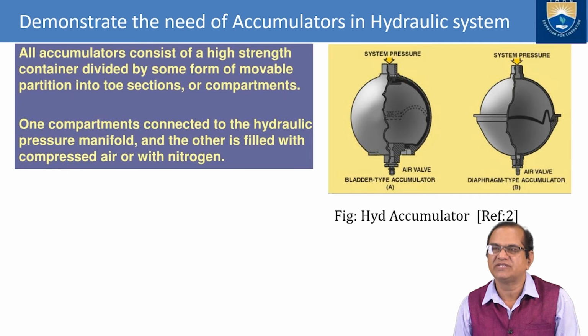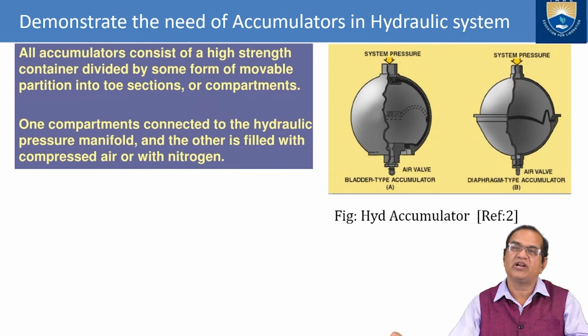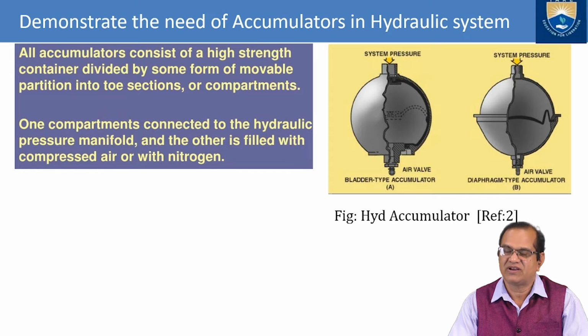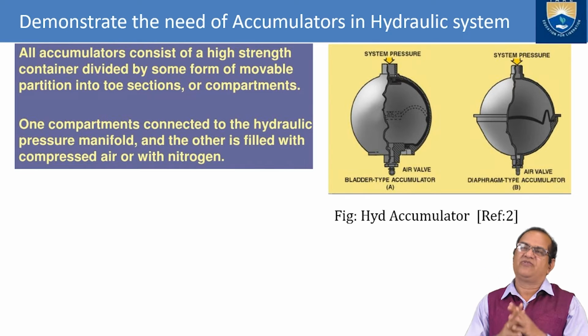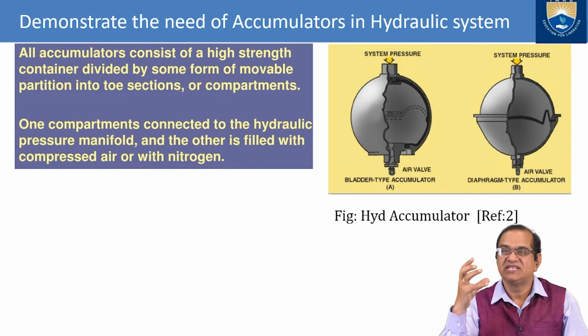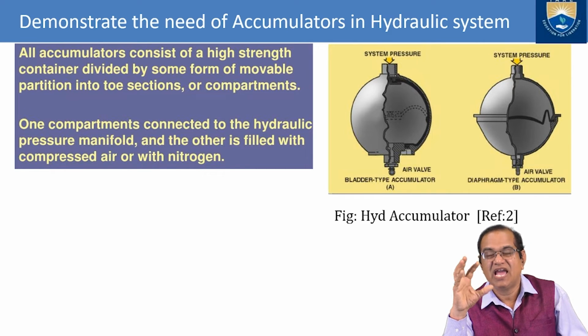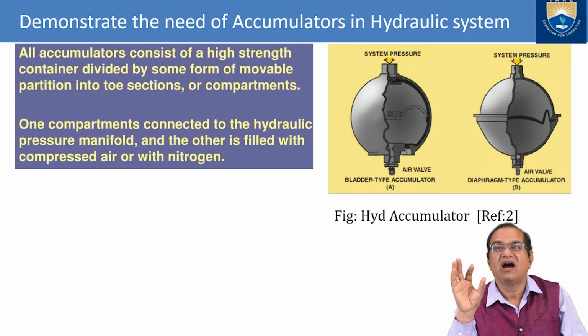Next very important item is to demonstrate the need of accumulators in the hydraulic system. You might have observed in our water system, we use some accumulators on the piston type of systems. If the pressure is high, these accumulators store the energy, and as and when the system pressure is low, they will release the hydraulic fluid at high pressure.